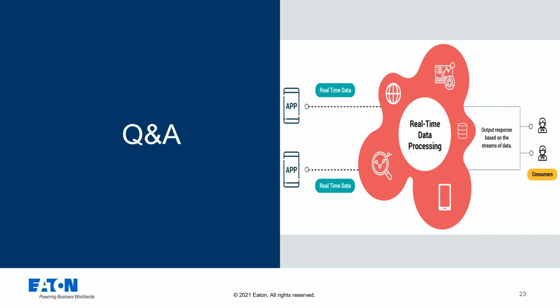Okay, so that has a twofold answer. Let's go with your basics. You have your sensors connected to a server which runs OPC, right? From that OPC, we can get that data pushed to a cloud platform, and then you can get a dashboard made. There are different organizations that could do it for you, but at the core, you would need a mirror OPC system or server to do an OPC to OPC integration to move the data.